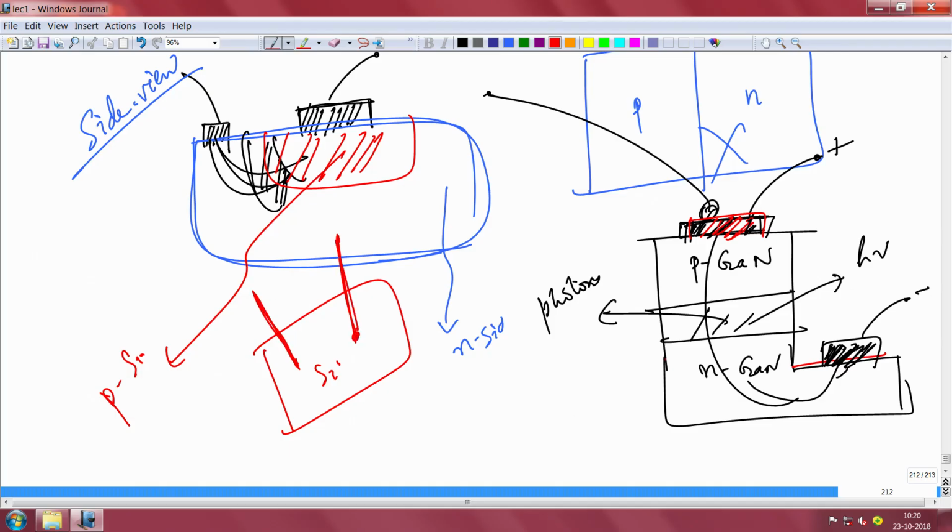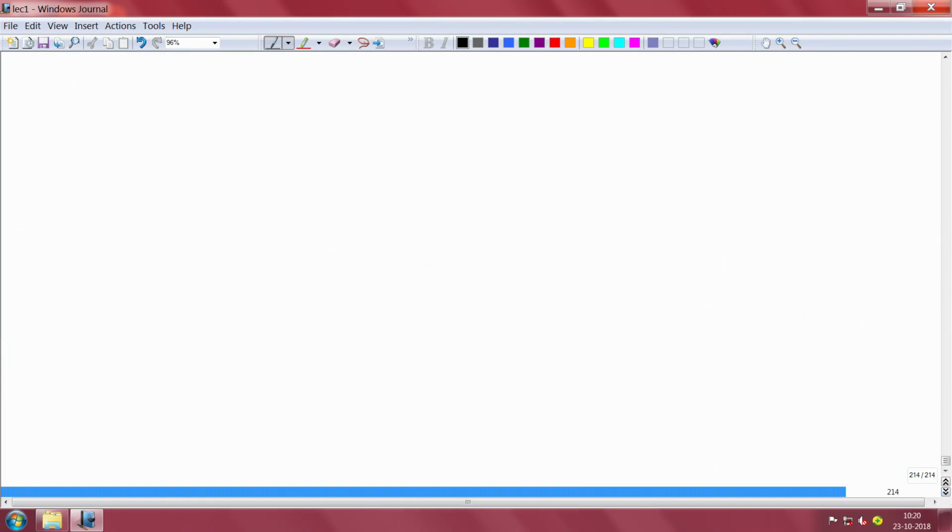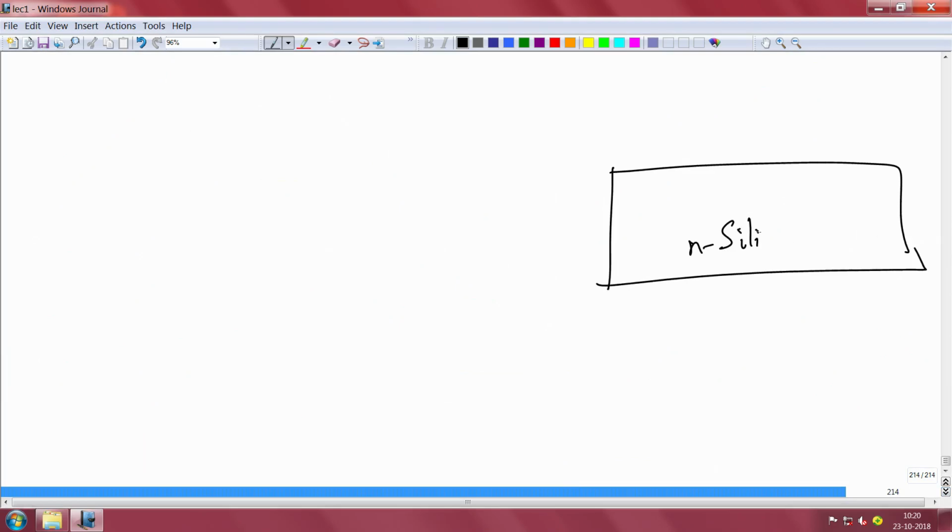So the contact you form, you cannot change the nature of the contact, whether it is ohmic or Schottky, right. So you need to put a pad down, you need to put a pad and bring the probe tips down, okay. And secondly, whenever you have a semiconductor, for example, suppose I take a piece of silicon, and I am taking the side view of a silicon wafer. So this is the side view of, say, n-type doped silicon, okay.